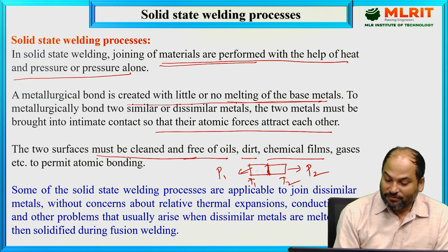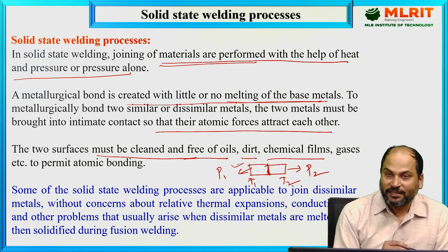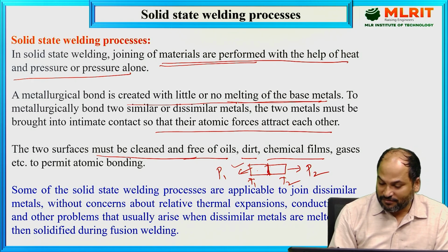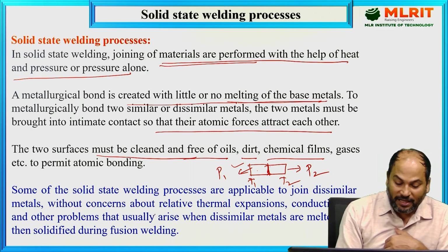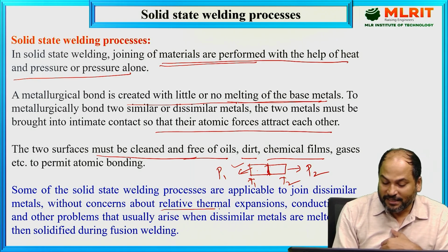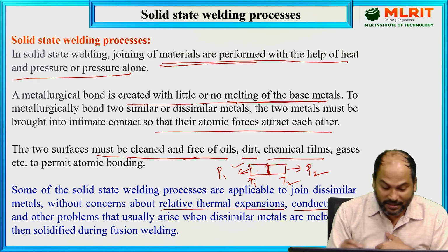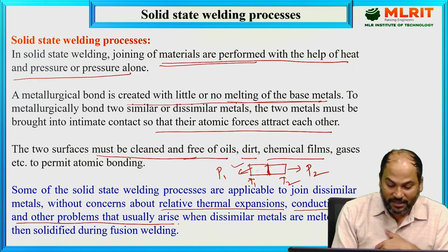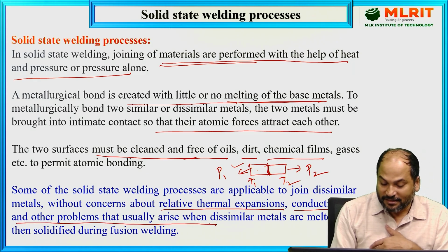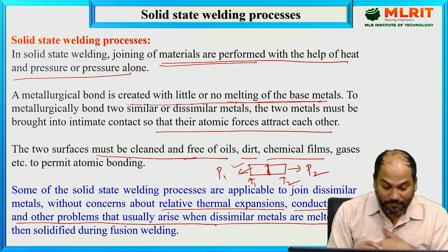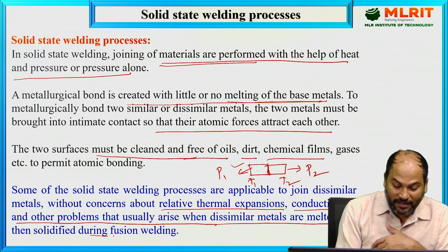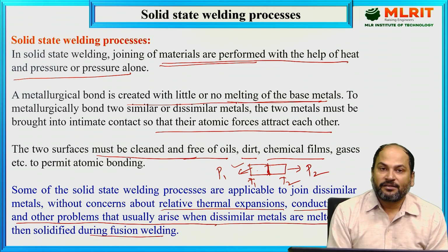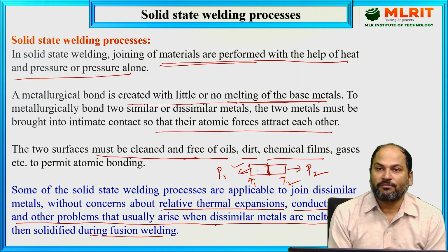So in solid state welding, it becomes very easy to weld. That's what has been given here: applicable to join dissimilar metals without concern about their relative thermal expansion, conductivities, and other problems that usually arise when dissimilar metals are melted and then solidified during fusion welding. Yes, this is the most important property of this process.